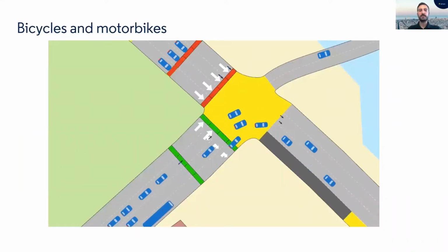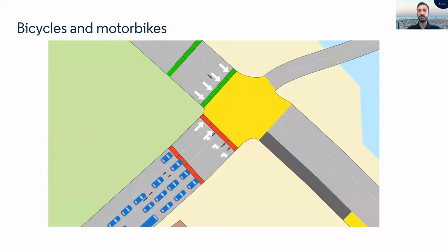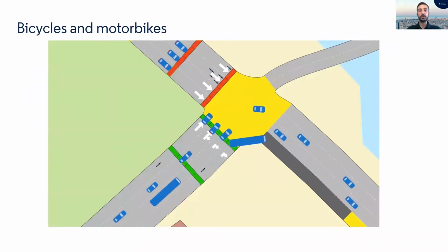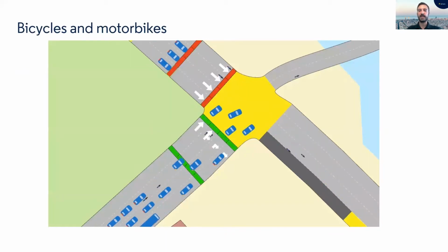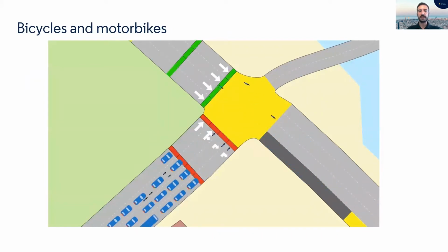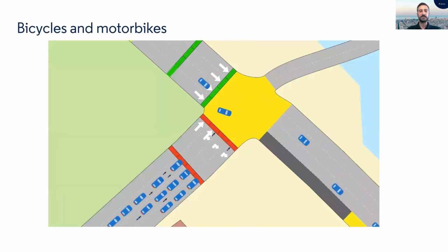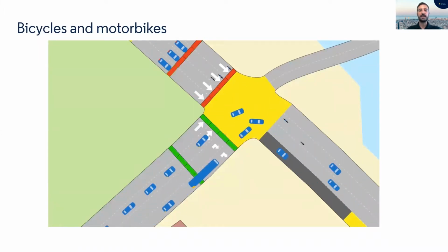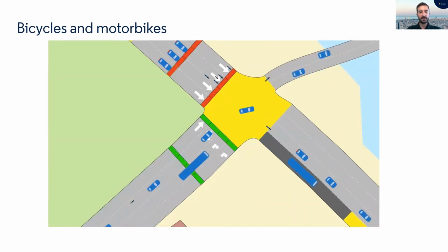We are introducing how bicycles and motorbikes move and interact with the traffic in urban and interurban roads. A new specific behavioral model for bicycles and motorbikes, which is only available in the microscopic simulation. This new car following model can model the lateral and longitudinal movement of vehicles that don't follow the lane markings. Bicycles and motorbikes perceive the road surface as a bidimensional space, compared to the four-wheel vehicles that perceive it as monodimensional. Let me better explain this.